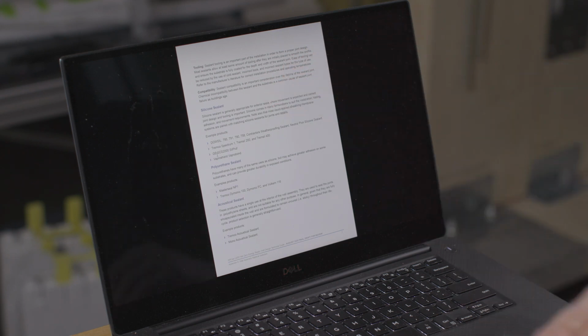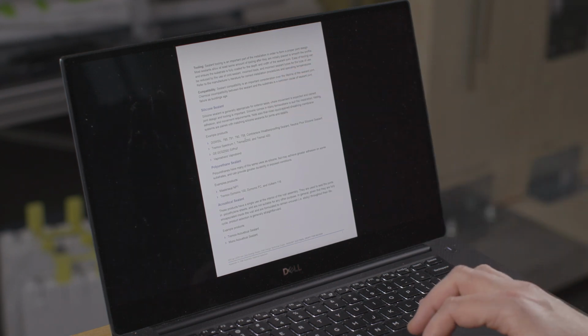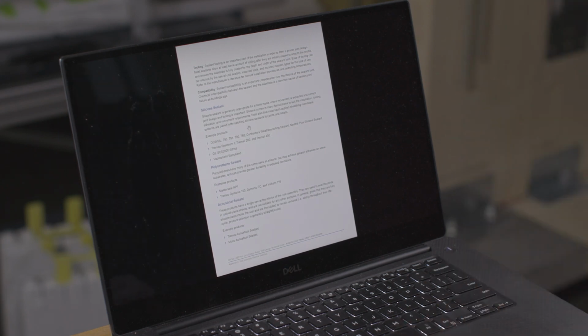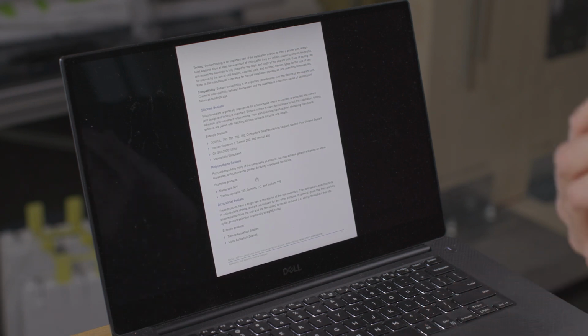They tend to last the longest out of any sealants, just because of the chemistry. And so silicone sealants are typically used in exterior applications. Polyurethane sealants are really good at adhesion and cohesion to surfaces, but they don't necessarily last as long exposed to UV and heat.